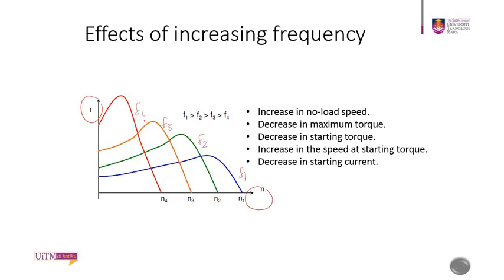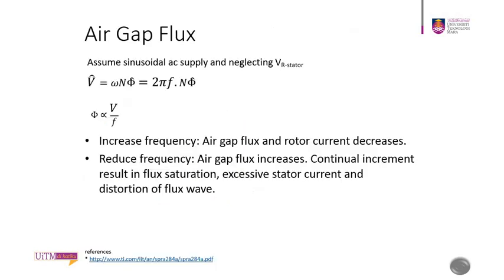So you have an increase in no load speed, but a decrease in your maximum torque. You also have a decrease in your starting torque, and an increase in the speed at the starting, but a decrease in the starting current. That will be the effects of changing the frequency.